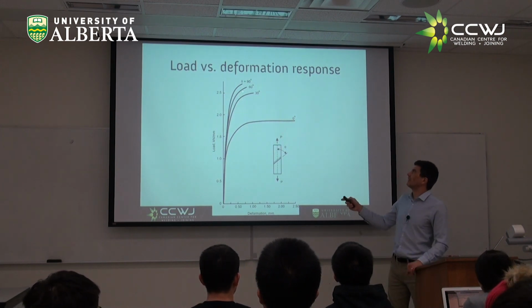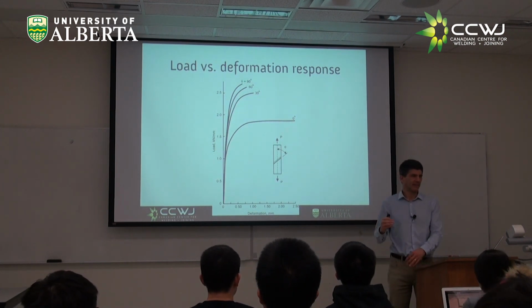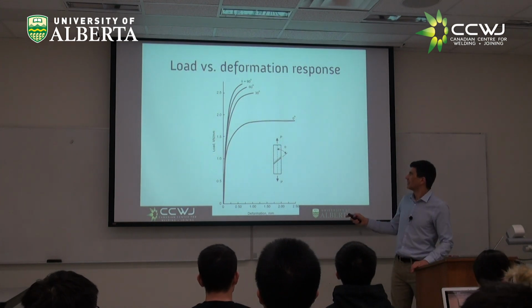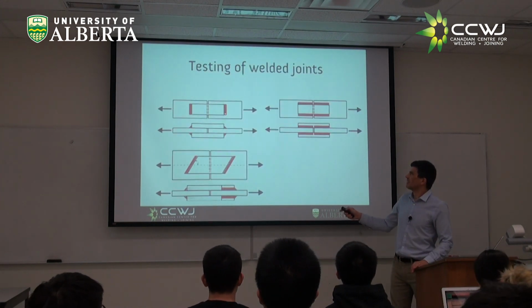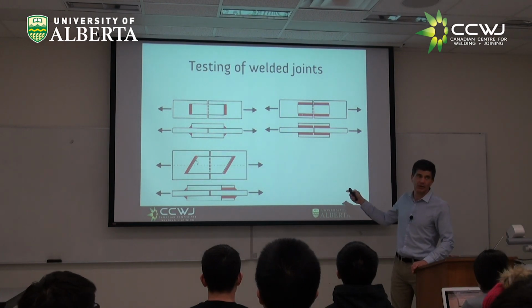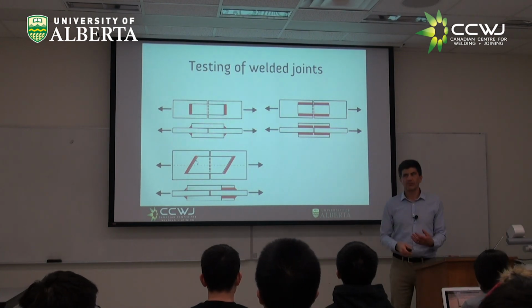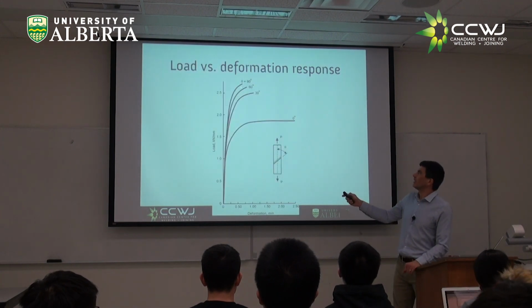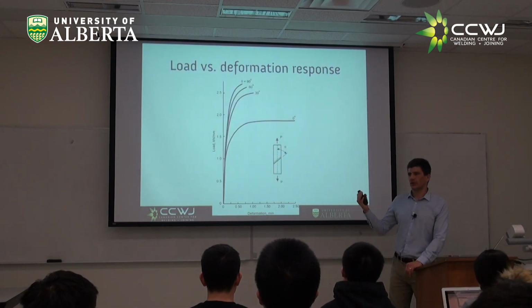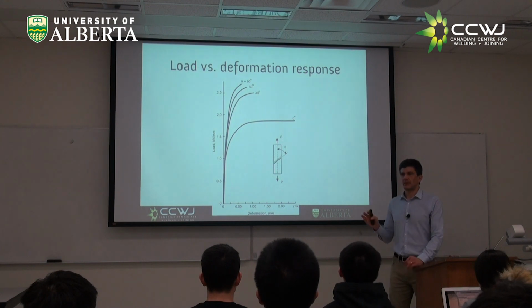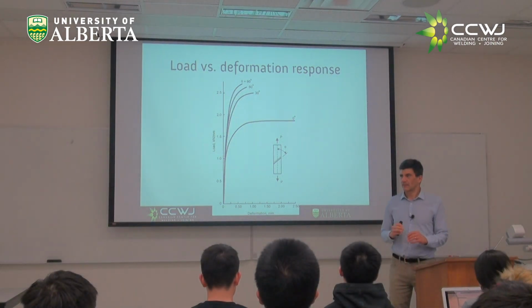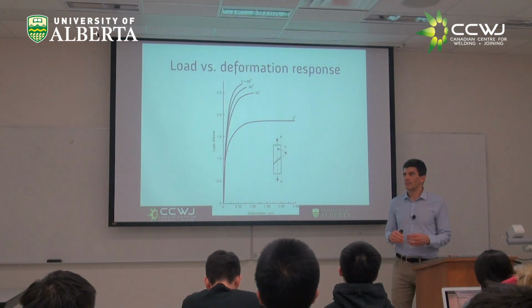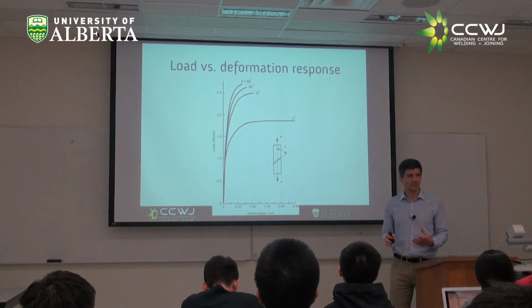But you had this insight that I thought was fantastic. The transverse is less ductile, right? Because you have a smaller characteristic length to deform. This one could deform over a long length. But the trade-off of being more ductile is that it's less strong, right? So transverse welds are stronger, but longitudinal welds are more ductile. Same material, so this is not a material property, but a system property.